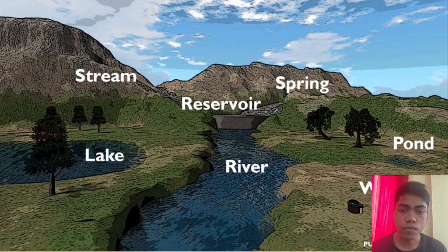The first process involved in water treatment is water pump intake. The water source used to supply the water pump is often from a local river, lake, or reservoir. A series of pipelines and pumps transport the water to the treatment plant. At the treatment plant, larger pumps are used to transfer the water up to where all the treatment facilities are placed. Engineers make use of gravitational energy to help the water flow while reducing water pumps' running costs.